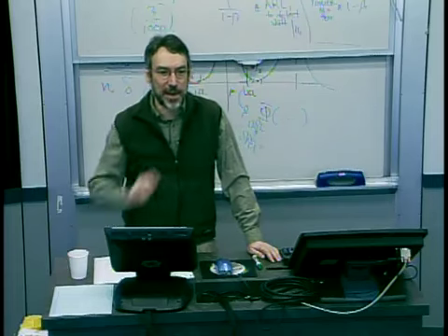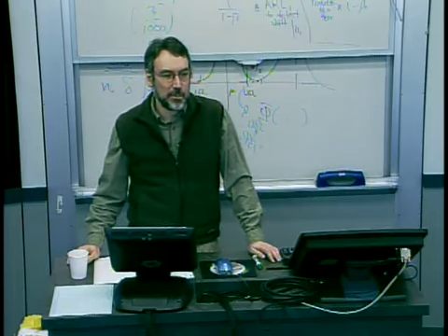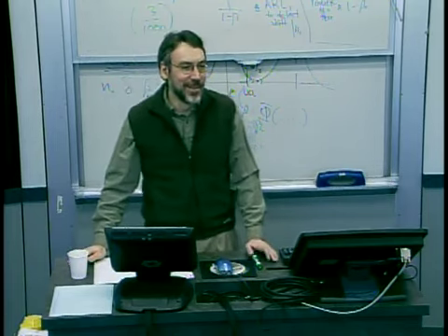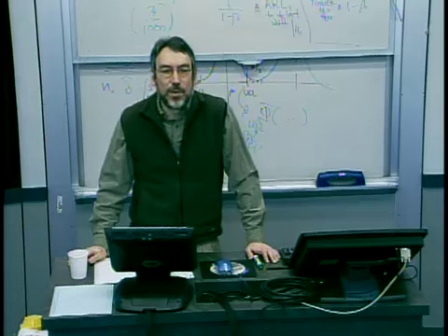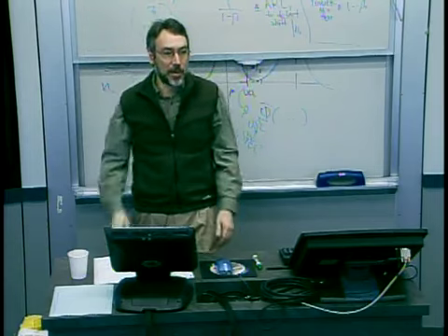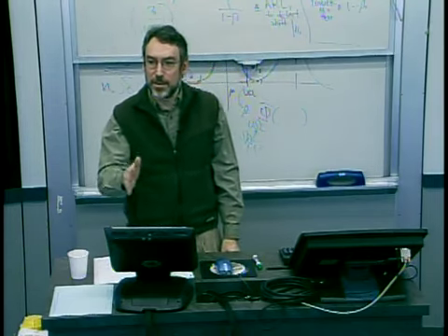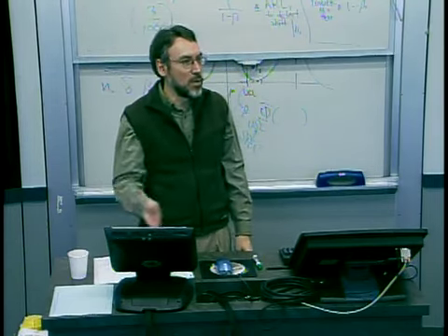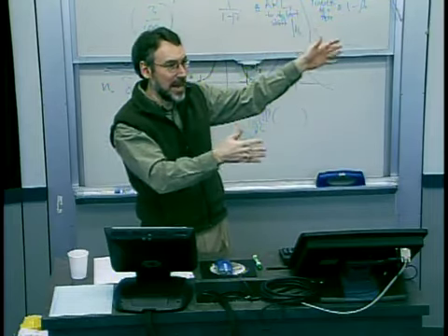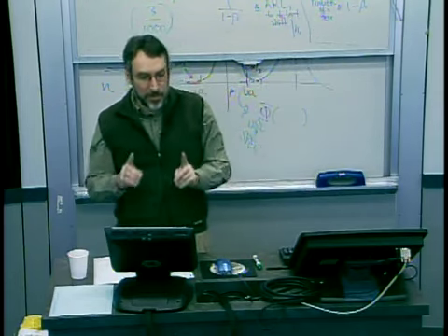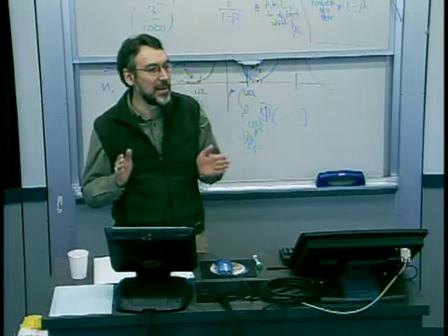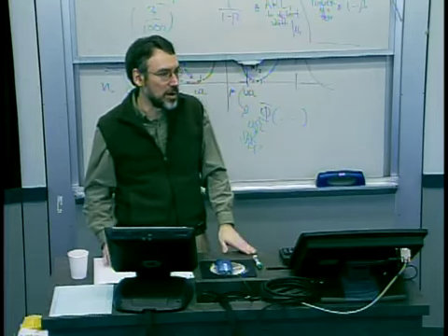I'll tell you the number one thing I would do. Look at the screen. Pull the power plug. Plug it back in. No. I would, yes. Check the measurement. Yes. That's exactly what I would do. I would always doubt my measurement equipment first. They also have failures. Rather than pull the process, turn the process off and panic with the actual equipment, I'd want to verify the measurement first. So I'd take it off, do an independent measurement of those parts and try to understand it.